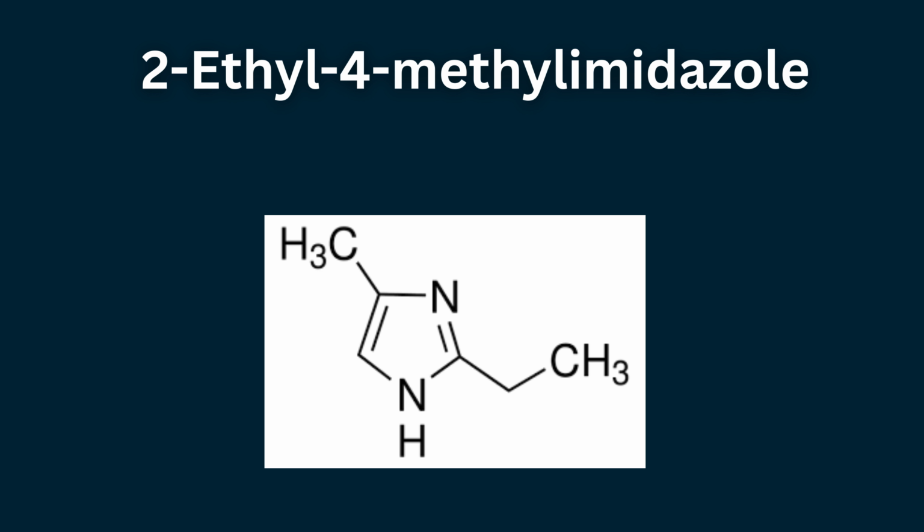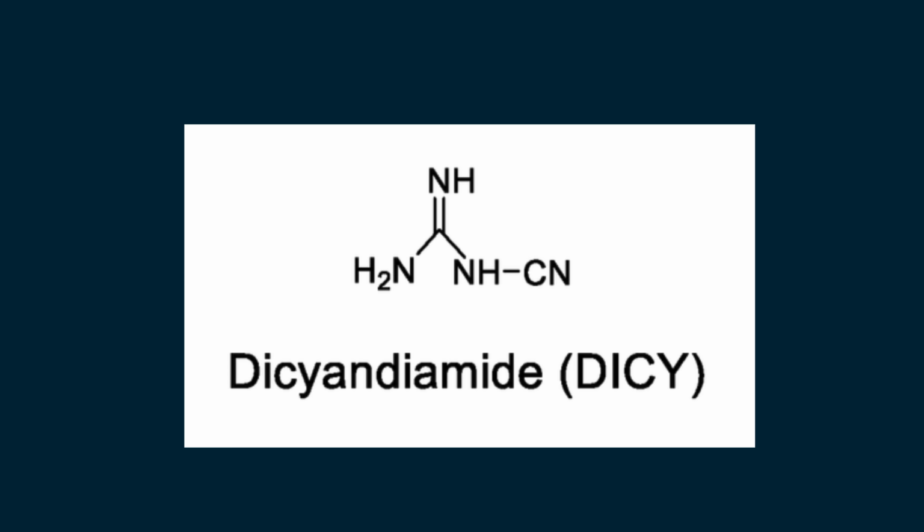Imidazole catalysts. Substituted imidazoles such as 2-ethyl-4-methylimidazole, EMI, are widely used as catalysts or accelerators in epoxy formulations. EMI is a viscous liquid with a high boiling point and can cure epoxy resins at relatively low temperatures. These catalysts produce densely cross-linked networks with good adhesion to metals and improved thermal stability compared with tertiary amine catalysts. Latent imidazole catalysts have also been developed for fast-curing adhesive systems.